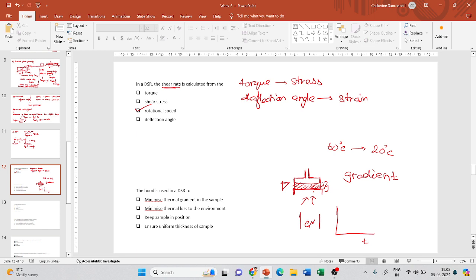So what ASTM says is, a simple way of doing it is, you measure the modulus by applying a very small strain value for some time, and plot it against time. So at 60 degrees Celsius you expect the sample to have a lesser modulus, right? And at 20 degrees Celsius, obviously the modulus of bitumen will increase.